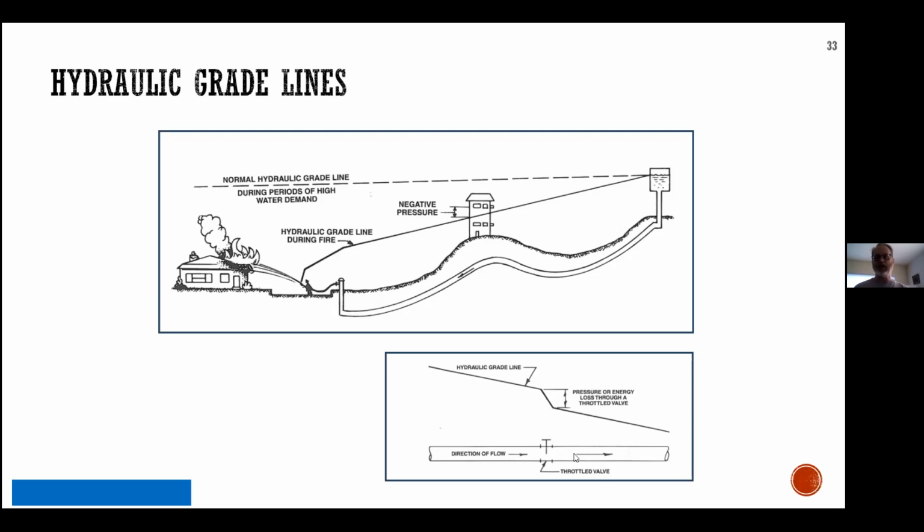You could take a pressure reading on the outlet side or on the right-hand side of the valve, and on the left-hand side, and connect your clear plexiglass tube, and you would see this grade line dropping drastically because of the restriction in the pipe. And hopefully that wasn't you, the operator, that left that valve half closed.